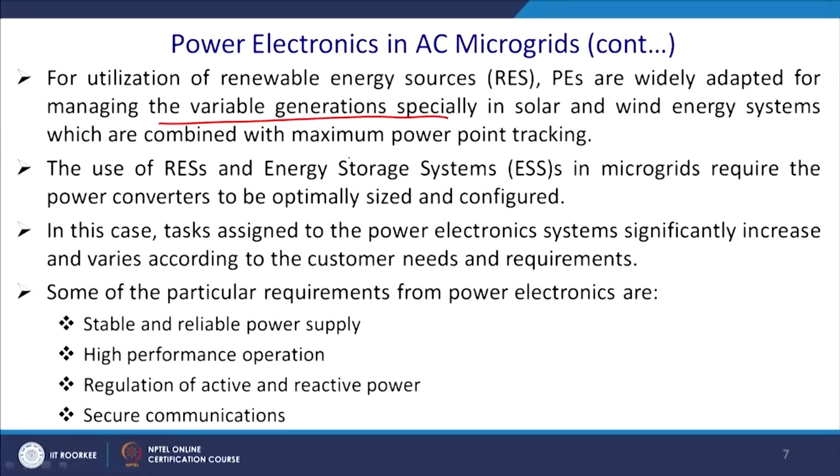So, we require to extract the maximum power because the efficiency of the solar panel is around 15% for the polycrystalline structures. Losing some efficiency would be a great hindrance in using the solar panel. For this reason, solar power has to be tracked by MPPT.